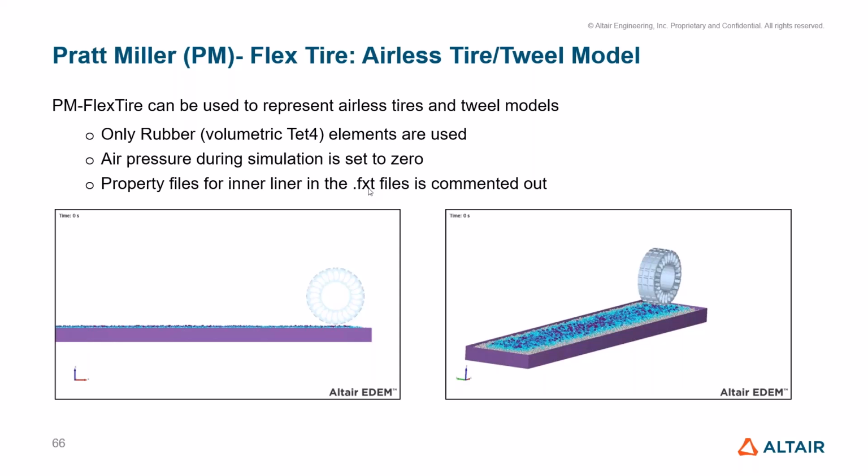You can go through the lubrication contact model reference information and, if it fits, choose that model as well. However, either the high cohesion or the lubrication model will only give you a direction, because they are not the right models, since 40% moisture is generally a slurry condition.